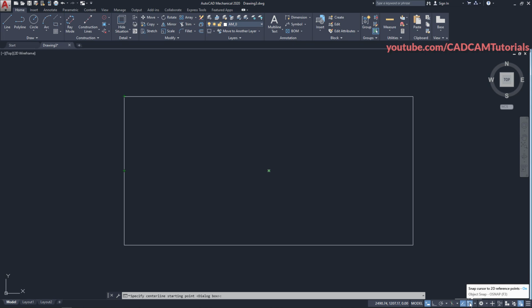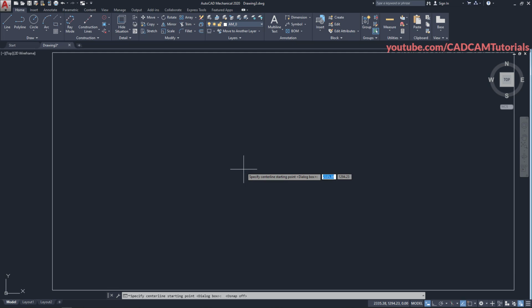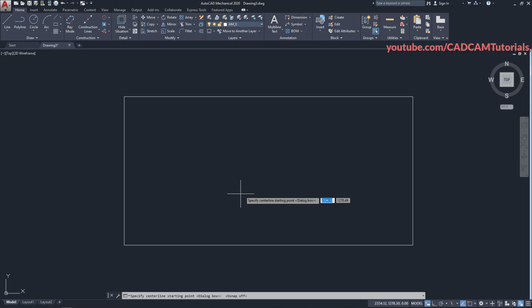automatically. So here is that object snap option. As it is shown in blue color, therefore it is showing the object snap automatically. If I turn it off, and to remove these markings, just zoom it once, zoom plus and zoom minus, so it will remove it. Now if I take my cursor here, it is not showing me any object snap because my object snaps are turned off.